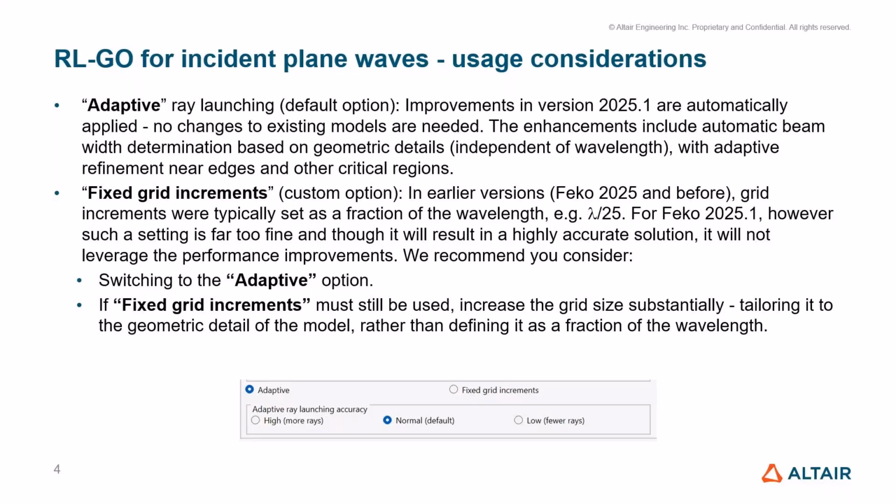However, for those using fixed increment mode, we recommend that the increment be chosen relative to the geometric scale of the model rather than the wavelength, because smaller increments may unnecessarily increase the runtime without any corresponding accuracy gains.